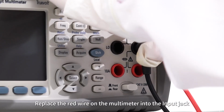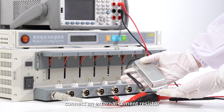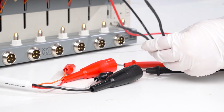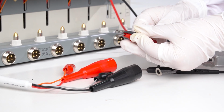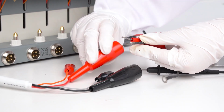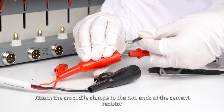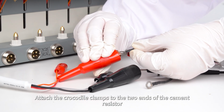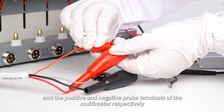Replace the red wire on the multimeter into the input jack. Then, connect an external cement resistor. Attach the crocodile clamps to the two ends of the cement resistor and the positive and negative probe terminals of the multimeter respectively.